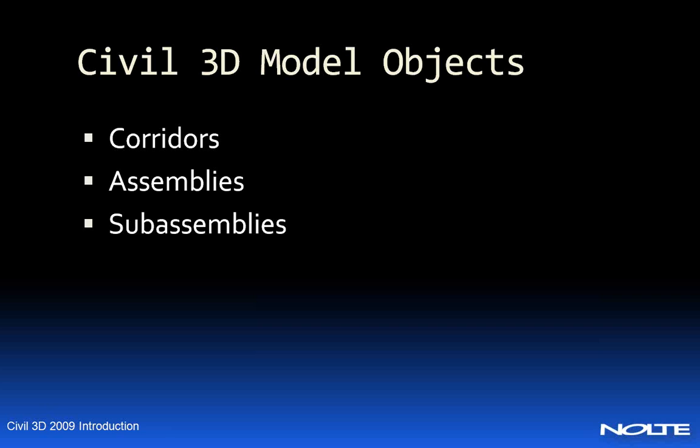Assemblies are built from subassemblies, which are predefined objects that we can drag and drop and edit parameters to build up what our roadway cross-sections look like. So it's kind of like doing templates in Land Desktop, but you don't actually draw the template. You pick the components and you add values to their properties and create your models that way.